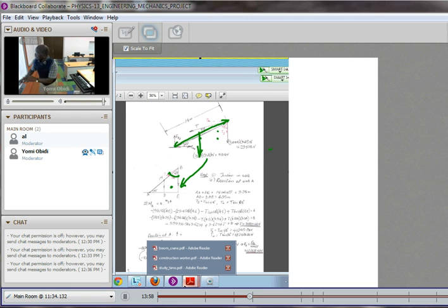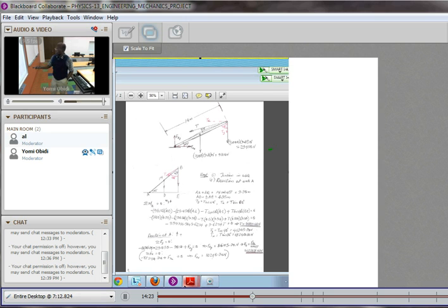So let's clean this up and focus on the geometry now. Let's take care of the geometry. We find the length of AE and the length of BE. AE is BE only because this is 45 degrees. If it was a different angle, we would look for the different lengths. So we know AE is BE is 14 cosine 45 degrees. We do the same thing with AD.